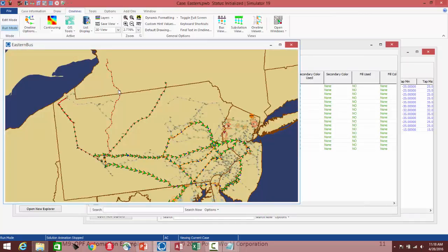The display auxiliary file format is powerful, because you can either add objects to a diagram or modify ones that are in there using a text file, which could be programmatically generated. So if you have data, for example, on line routings in some external database, you could program that external database to generate a display auxiliary file that you can then load into a one-line diagram to either draw or modify the objects on that one-line diagram.